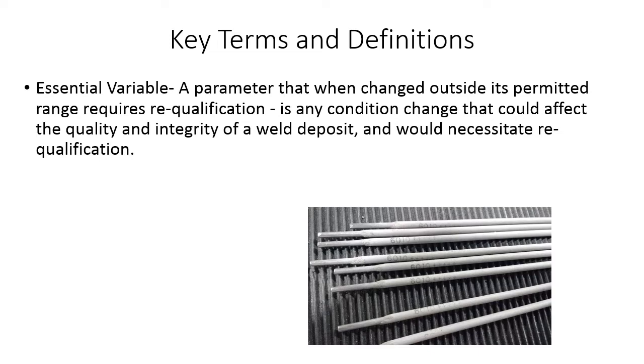An essential variable, if we change this, we have to requalify the weld procedure. And I've got a couple examples later on of essential variables that if you change those parameters outside of what it is listed as, you need to requalify it.